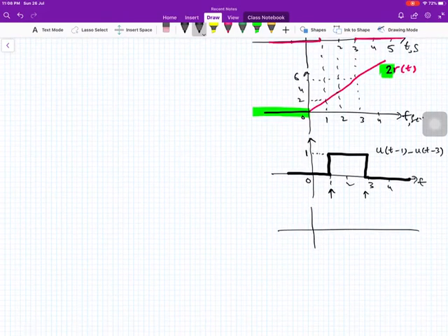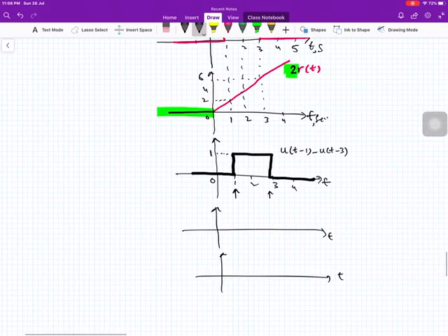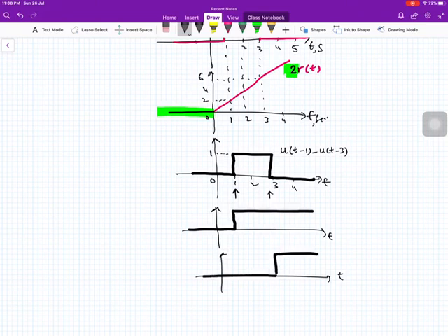What I am saying is, t and of course in seconds, and if I have a step function and another step function, this step function is u(t minus 1) because the origin is shifted to the negative side, and this is u(t minus 3), this is 3 seconds because the origin has been shifted to the negative side by an amount of 3 seconds.